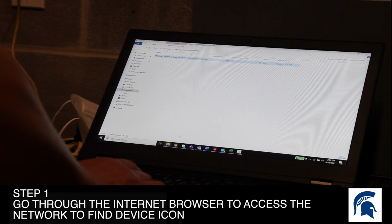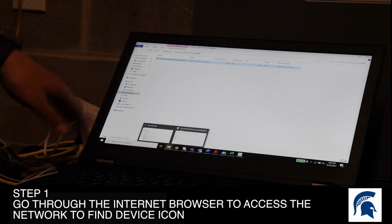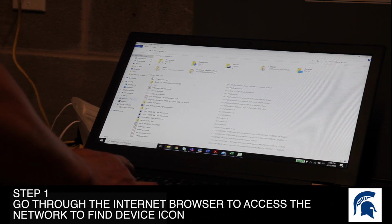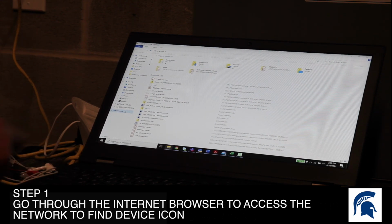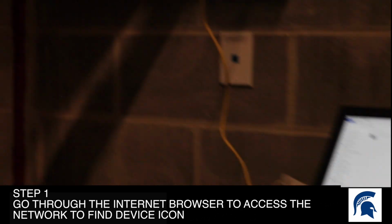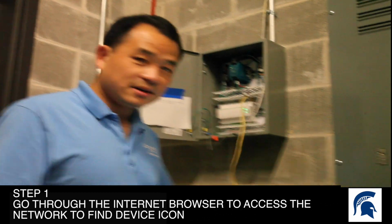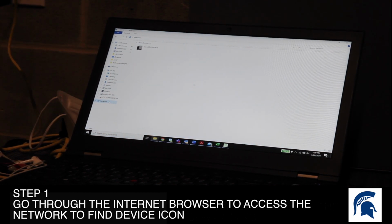You can open File Explorer from your laptop, and then go to Network to find this device. Once the power lights turn green, that means you have a solid Ethernet connection between the device and your laptop. Then click Network, and you see this device show up. They call it COMAX 510.